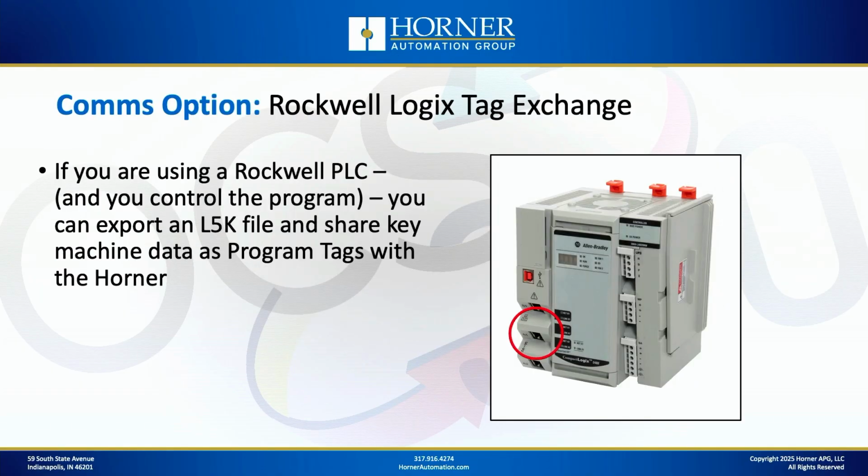Let's get started talking about the communications options, starting with a scenario where your existing machine is a Rockwell-based or features a Rockwell-based PLC or controller. In this scenario, there's probably a couple different ways to grab the data digitally or through communications. The first we're going to talk about is something called Logix Tag Exchange.